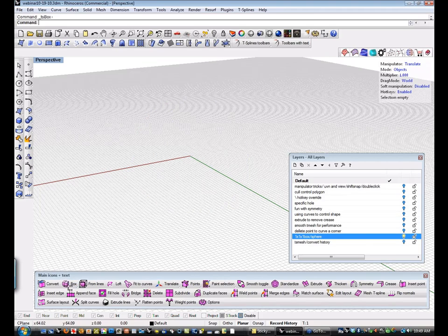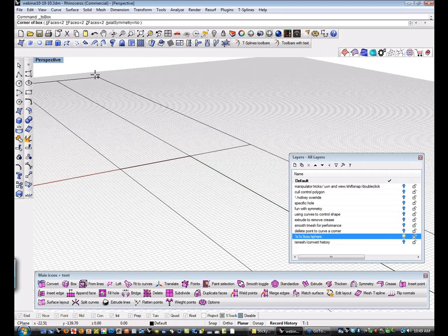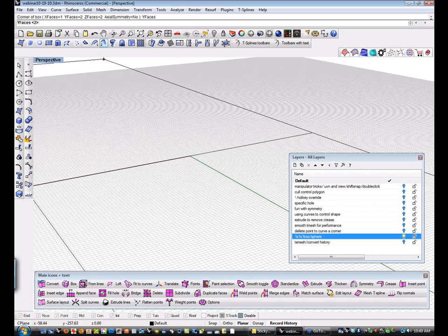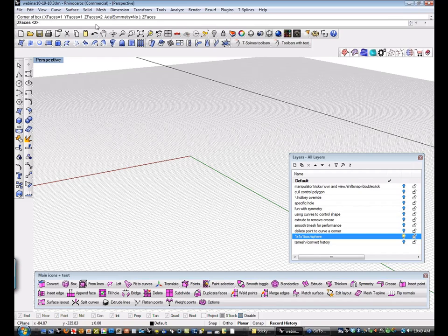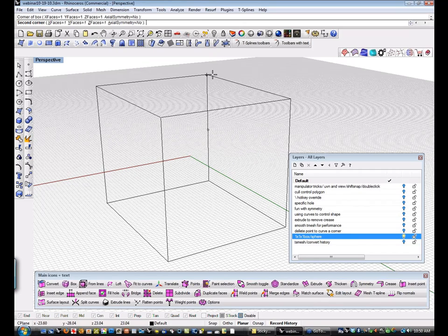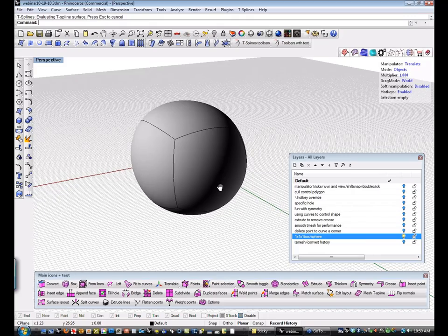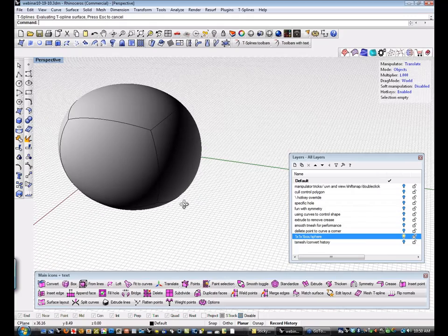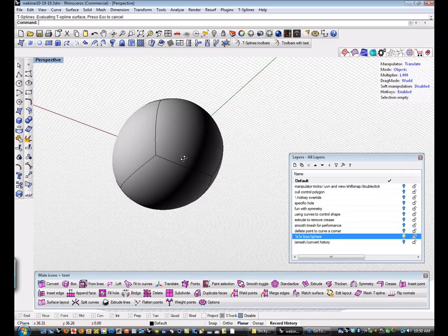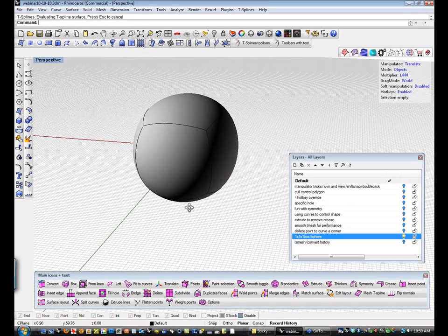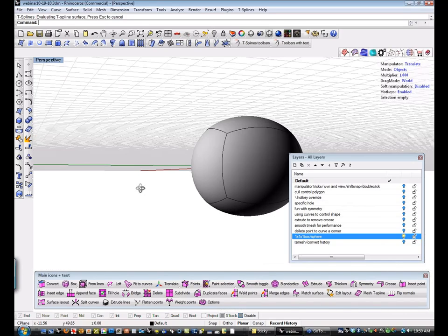And try this a different way. If I make a box, and if I set my face to 1, 1, and 1, so that I'm making a simple 6-sided box, you'll notice that smooth mode actually gives me, and if I would have set it so that it was use snaps so that it was actually square instead of rectangular, you'll notice that I get a much different topology for a sphere.